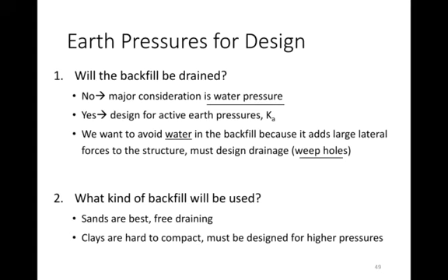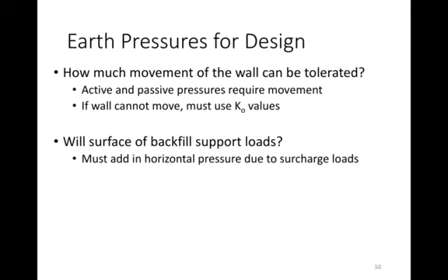And you're mostly concerned also about what kind of backfill will be used. The best is sand because it allows free draining. Clays are typically very hard to compact and they have higher pressures. You're concerned also about how much the wall is going to move. And the movement depends on which direction. Is it going to be an active or passive pressure?